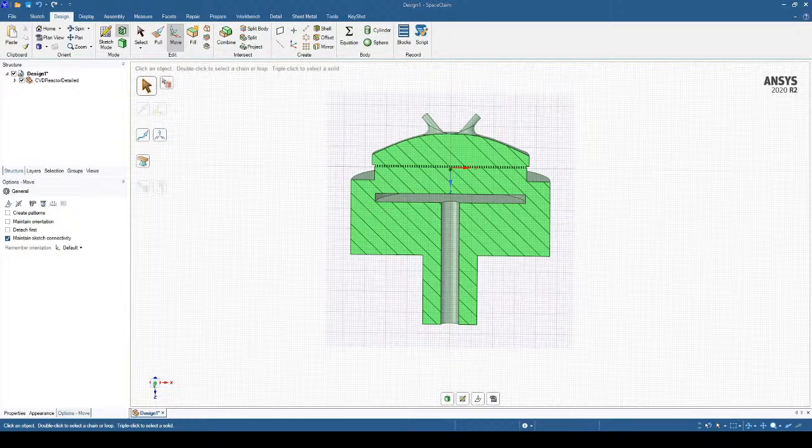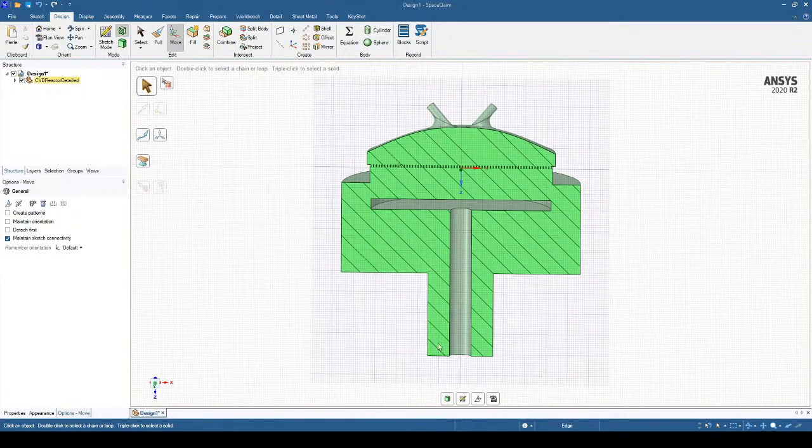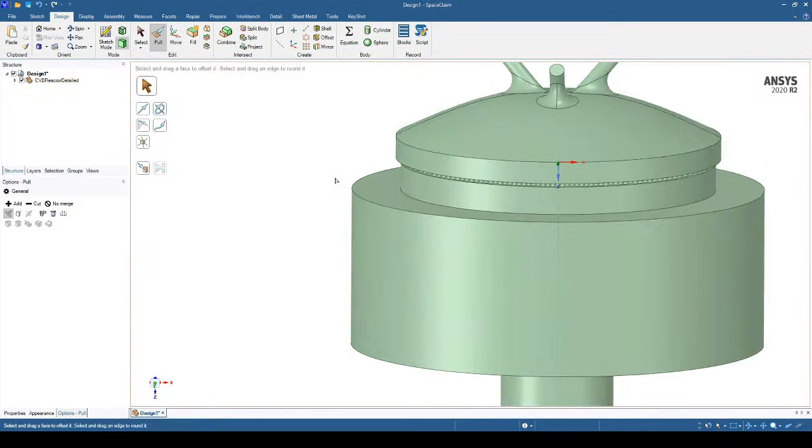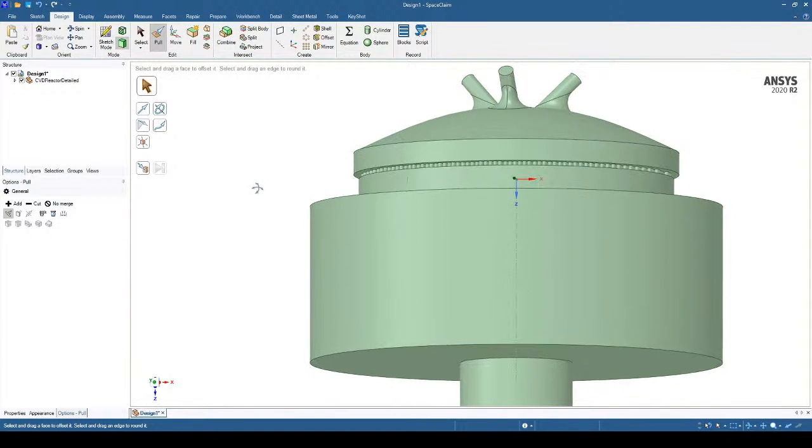The temperatures can be very high in these models, so controlling the temperature is important. Making sure the right temperature gradient develops inside of our model is important. You may adjust the pressure, the flow rate, the timing, maybe sometimes even put in a plasma field or a field to try to increase the mixing and the deposition rate. So with all of those controls, it's no wonder that these simulations become very popular. It's much easier to control all of these things in simulation rather than trying to build a lot of different devices and running various conditions to see what produces a smoother